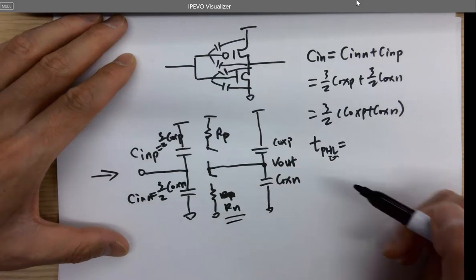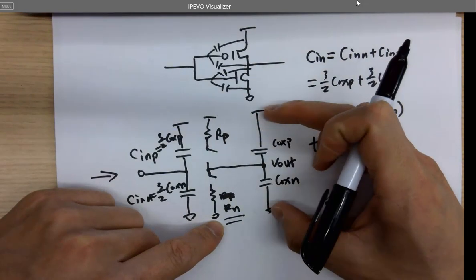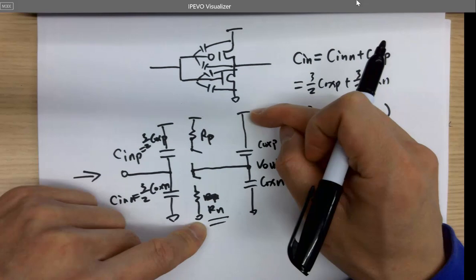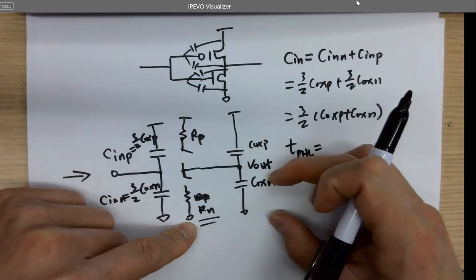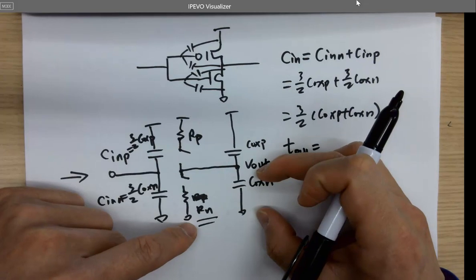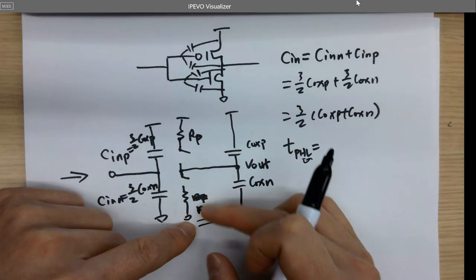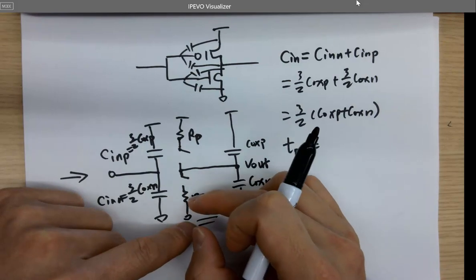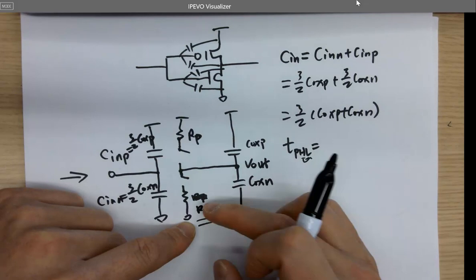So this resistor is getting engaged, and the two capacitors are getting engaged as well, because this is a DC source, which is the AC ground. So you have to rotate it and short it to ground. So you have two parallel capacitors, and this is the resistor getting engaged. There's a channel resistance of the NMOS, and this is off because it's H to L. Okay, so it's being put down to ground.